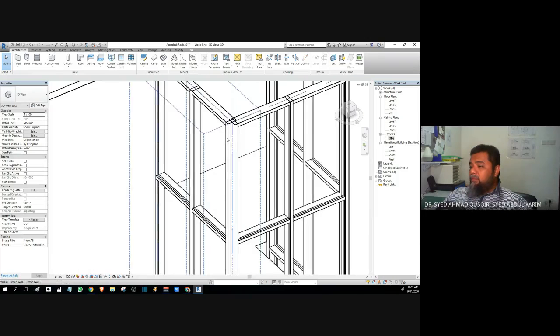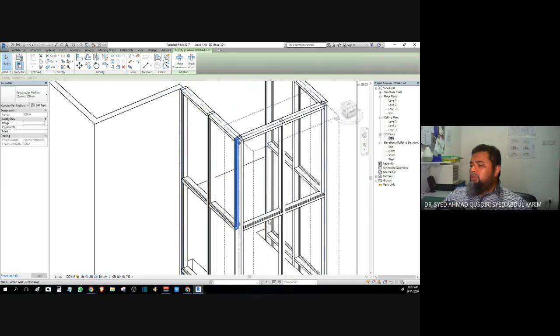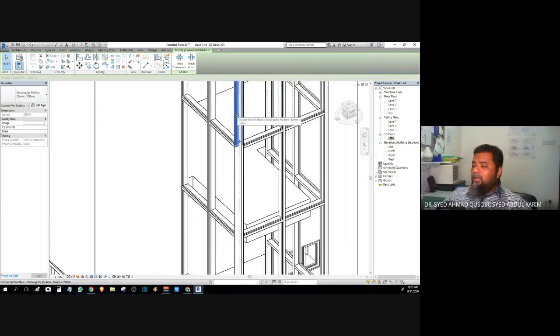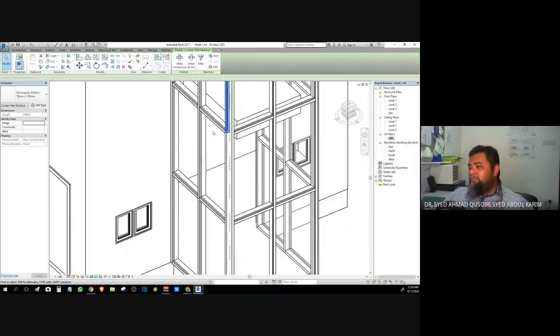As usual, when you're selecting something in Windows, you just click. If you can't seem to get it, you can use the tab button, but this time I got it. Now I want to also select the mullion at the bottom. Click here and it will highlight. To click the next one, you just mouse over where you want it to be and press the tab button. When it seems that that is the correct thing, don't click yet. Press the control key first, and don't let go. You can see the icon change into the plus sign, and then you click and release. So that's only the second one. Repeat the process. Go to the next one. Mouse over.